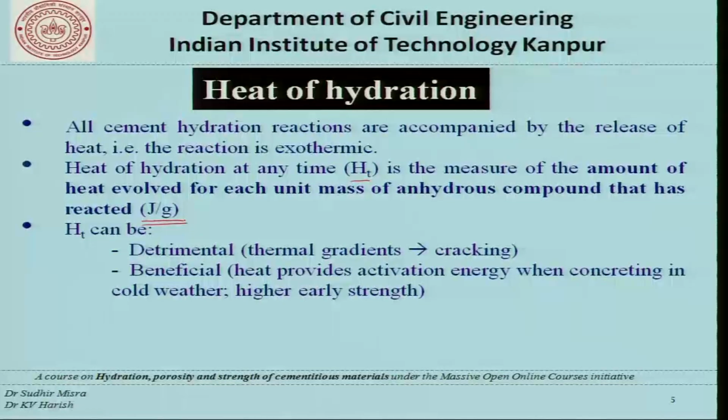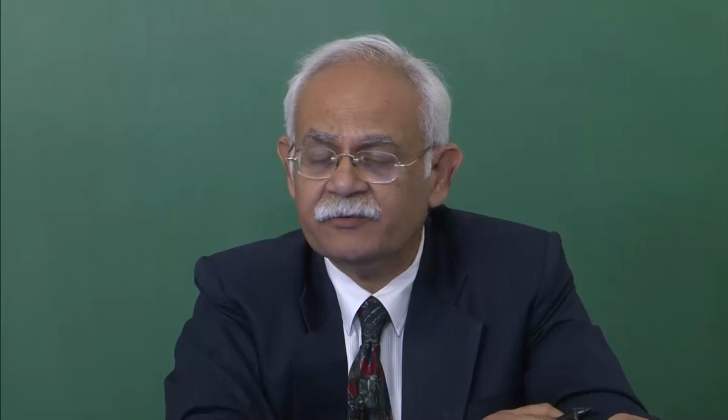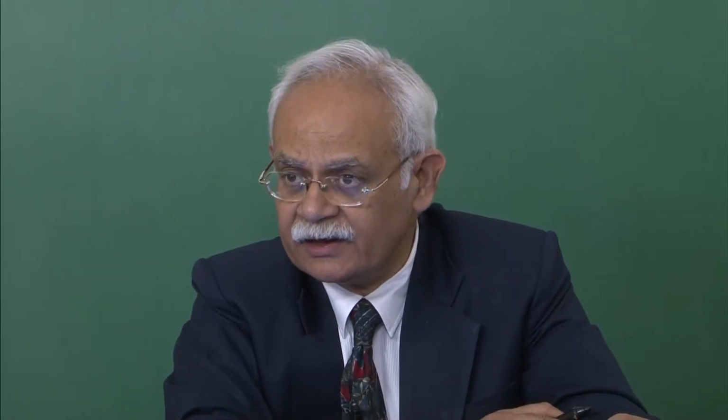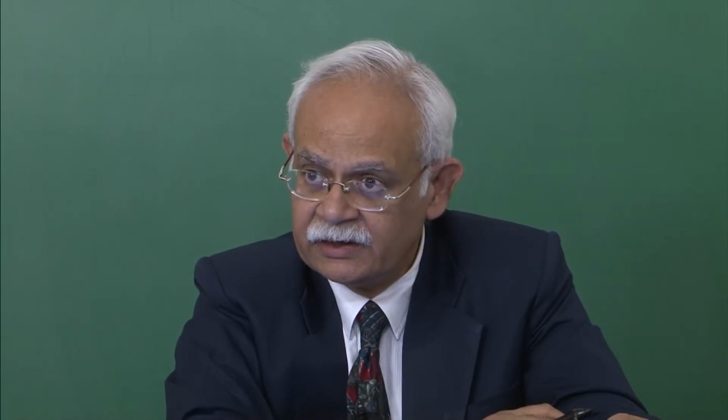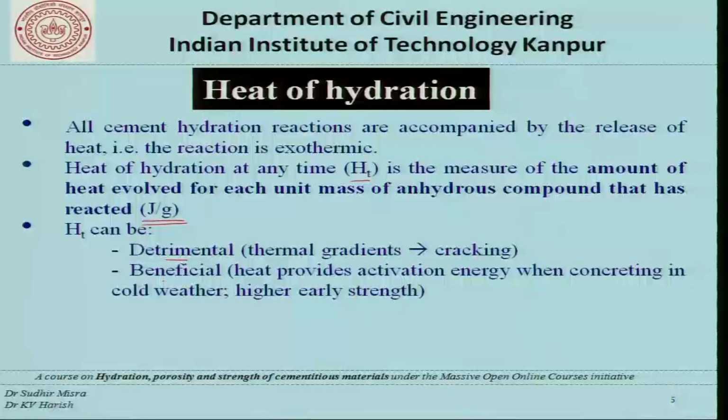Now, this heat of hydration HT can be detrimental, it can be harmful because it leads to the setting up of thermal gradients in the concrete and which finally leads to cracking, and that's extremely undesirable. However, in certain cases the heat of hydration could also be beneficial. For example, the heat provides the activation energy when concreting in cold weather or when we require higher early strength.